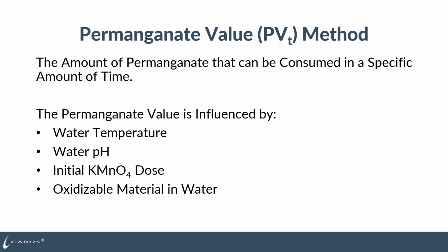So this will also take into account iron and manganese and taste and odor compounds in this jar test, because you're looking downstream after all those things are reacted. So you could come back and look at iron and manganese to make sure that's all removed during this process. If you were doing a taste and odor jar as well, you could then run your taste and odor jar to make sure that you're not having that taste and odor coming off the sample after you've treated it. And then it also helps determine how much permanganate's reacted with the organics as well.